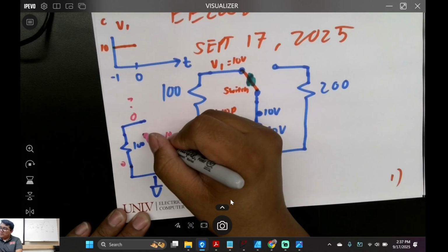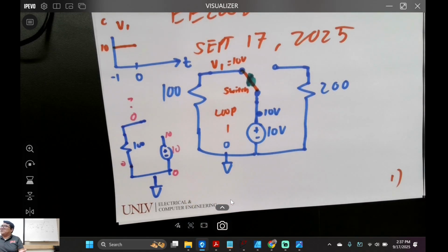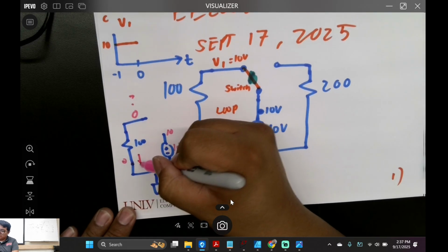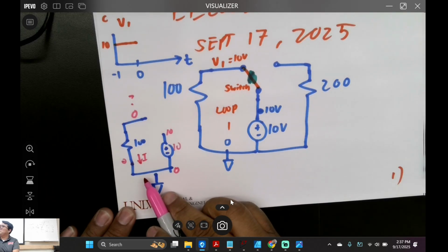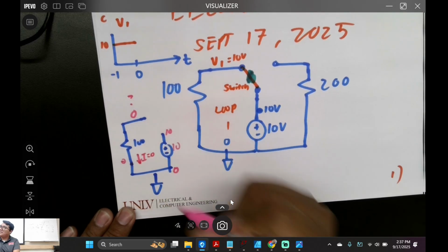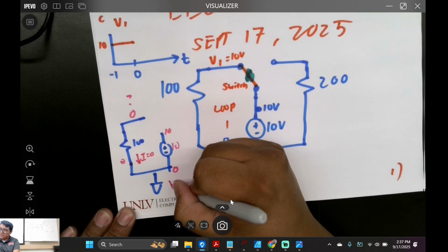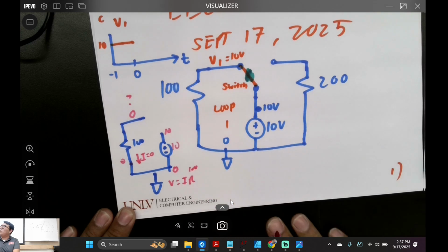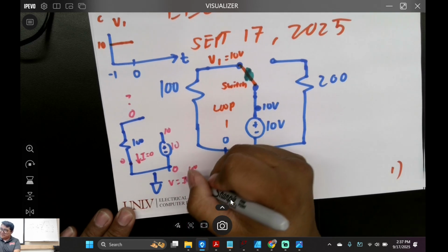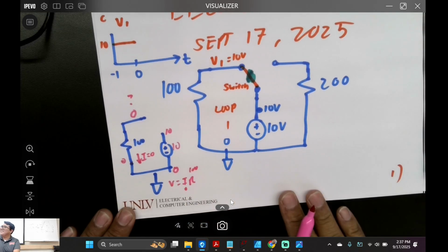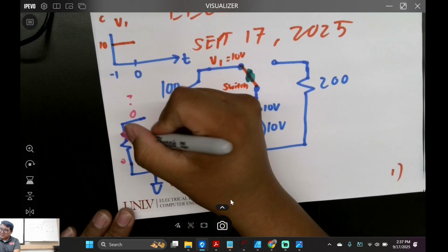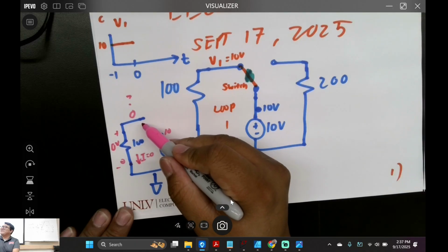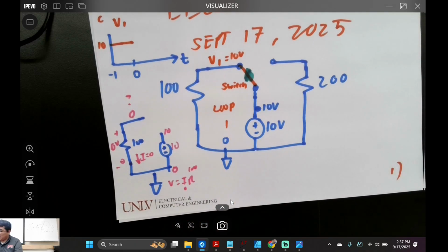So we just break the circuit, right? It's open, right? So that means there's no water flow. What's the current I here? 0, right? And then when we do V is equal to IR, where R is 100 ohms, and our current is 0, what's V? 0, right? So the voltage drop plus minus is just 0 volts. That's why this is 0. Does that make sense?